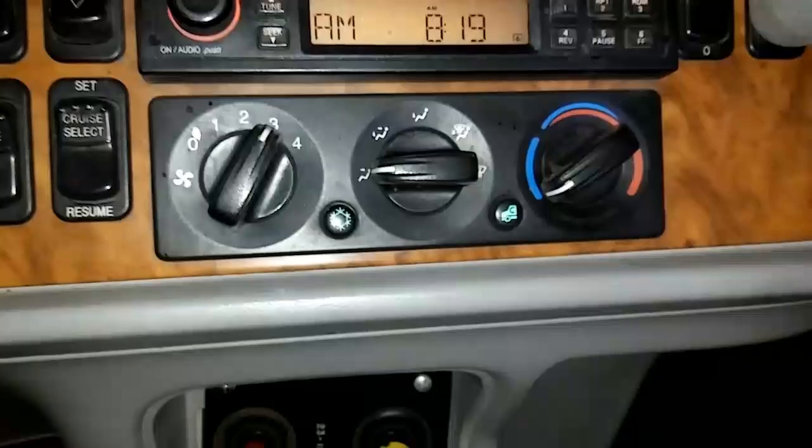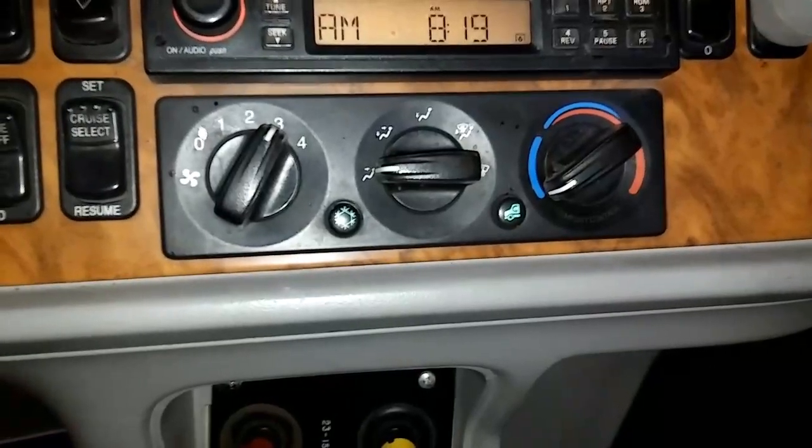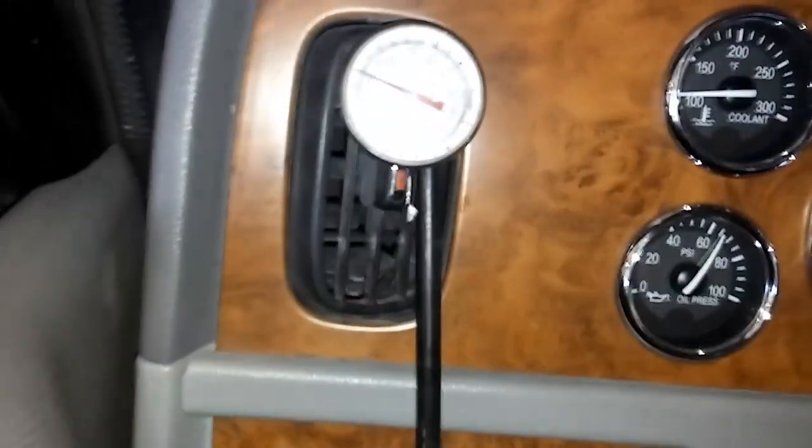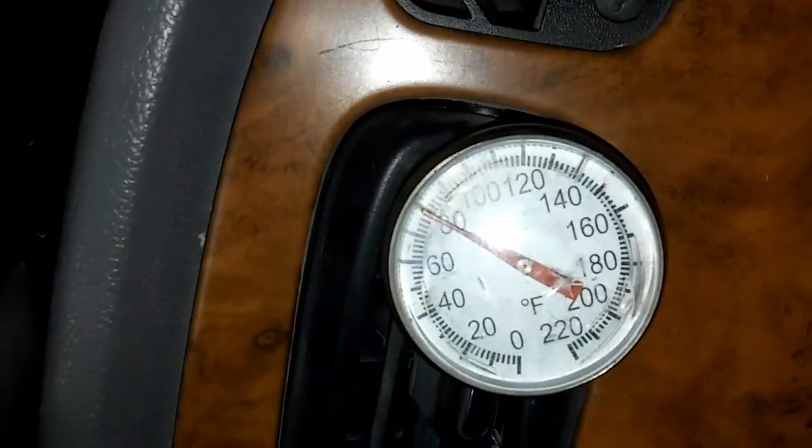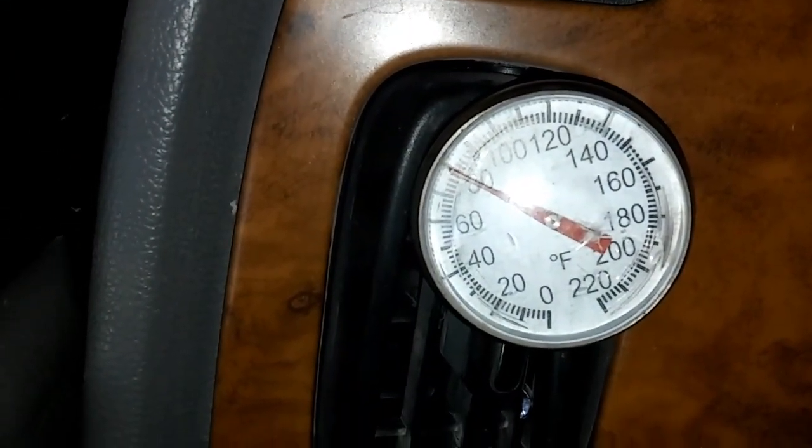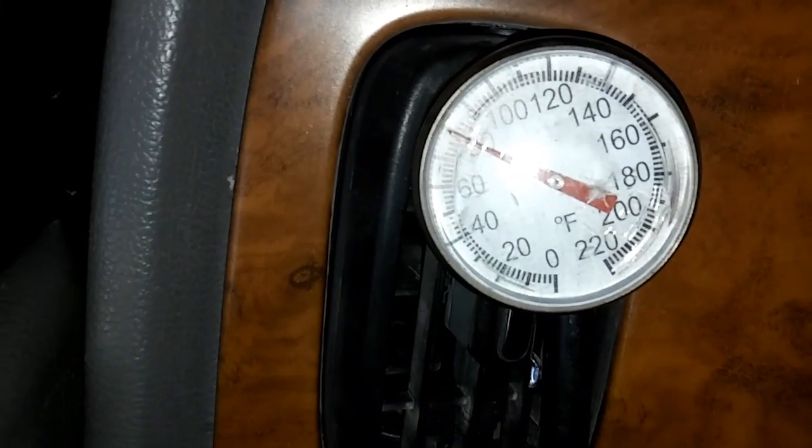You know, if you're trying to do this yourself, you're probably just going to have a set of gauges and hopefully a vacuum pump, okay? So let's get into the video. So this truck had come into the shop, and it wasn't particularly hot this day, but they complained the AC wasn't blowing cold. So the first thing I always do is put a thermometer in the vent, and sure enough, it was only blowing 80-degree air.